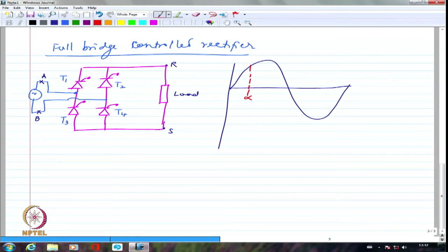Or I may be starting from 0, depending upon how exactly the circuit is working, whether resistance is dominating or inductance is dominating. Depending upon that, I may start off with 0 current, or I may start off with some finite value of current. Very clearly, if I am starting from rest, the current would start from 0. It cannot start from some finite value. If I am starting from rest, the current will definitely start off from 0 value, right? So let us say the current has started off with 0 value.